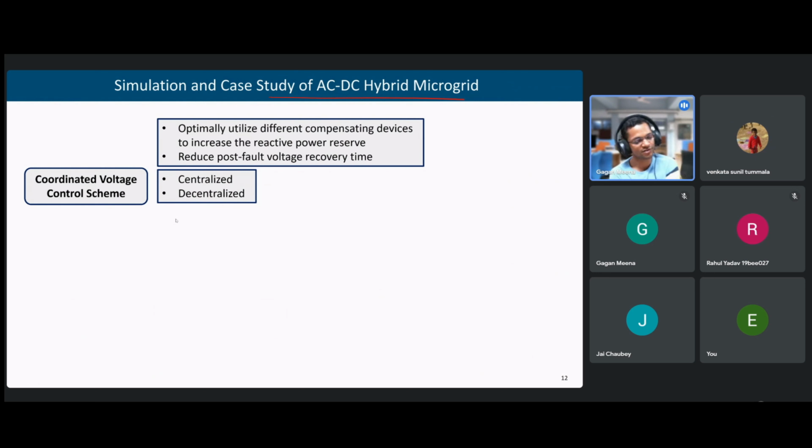Nowadays we use all these electronic equipments. We are facing many problems with the lighting system. There won't be any control over the lighting system, and if the voltage at the terminals shoots up, and at the same time these passive filters, capacitor banks, are injecting more reactive power to the grid, it will further exacerbate the problem.